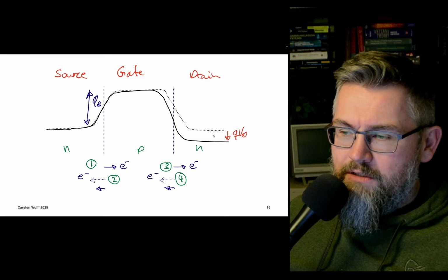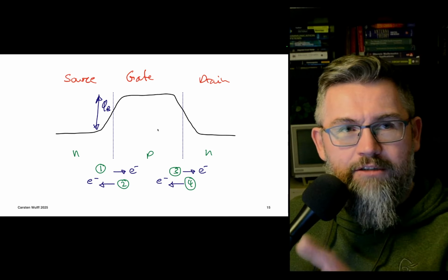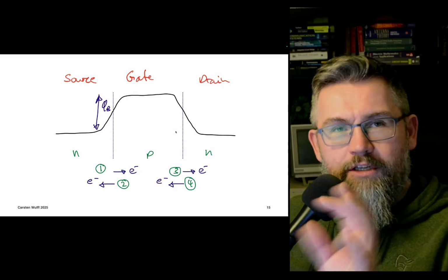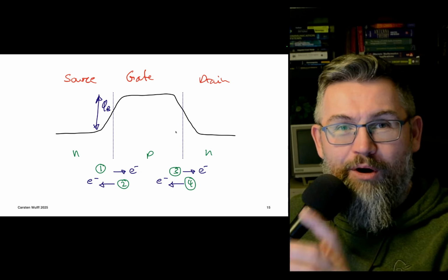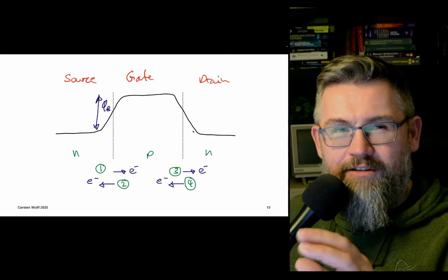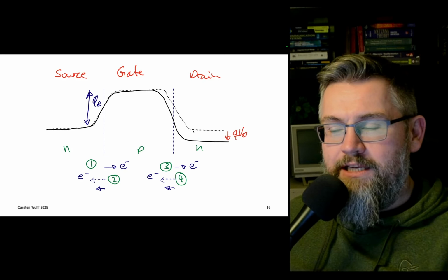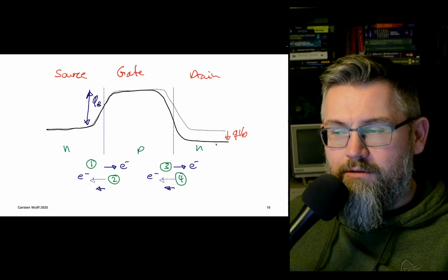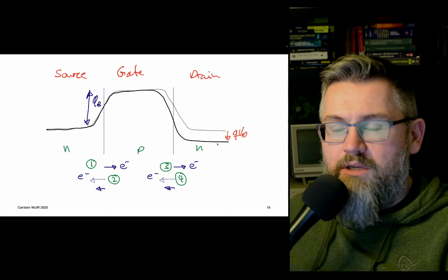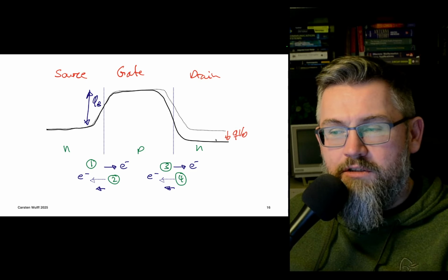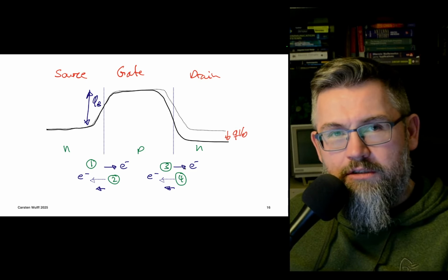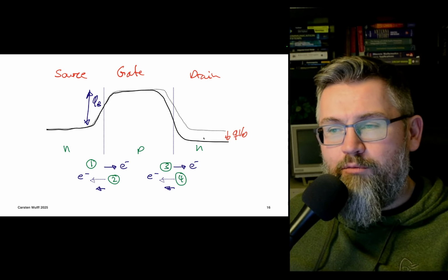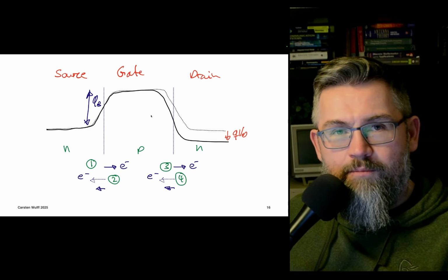As you start at the same potential on source and drain, then the current is not defined by this exponential behavior, necessarily. But as we increase the drain voltage, and maybe only at about 3 thermal voltages, there's almost no injection, comparably, from drain to the substrate of electrons.